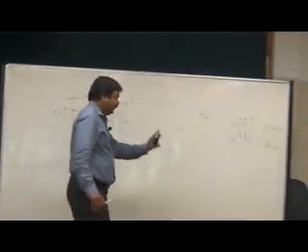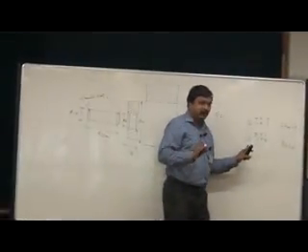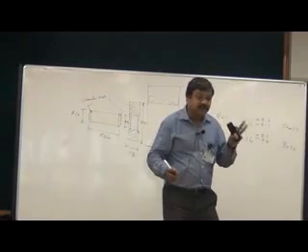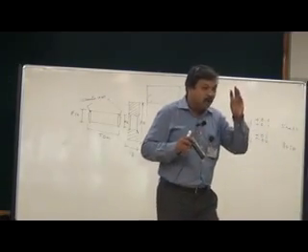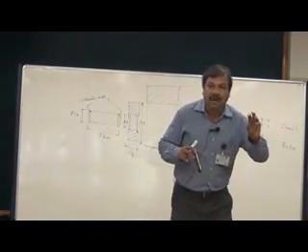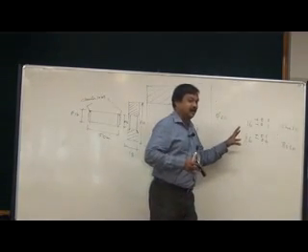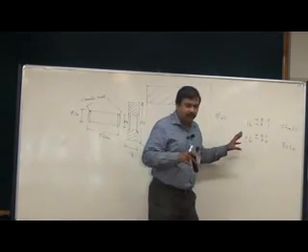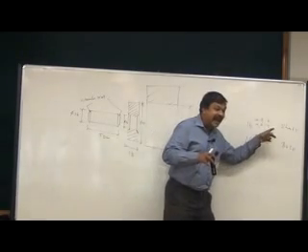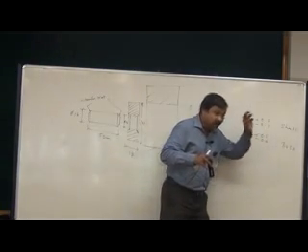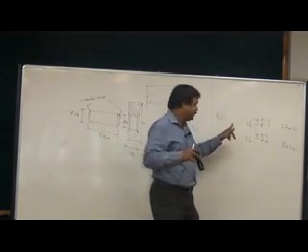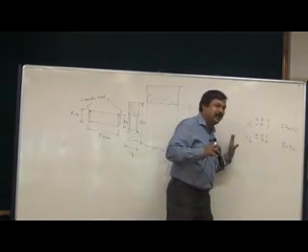What happens? See, the internal diameter of the bush can be anything in between 16 to 16.01. So the hole is not permitted to become smaller. The hole is permitted to become larger. On the other hand, the shaft is not permitted to become larger. The shaft is only permitted to become smaller. When I make the dimension like this, that is the meaning of it.